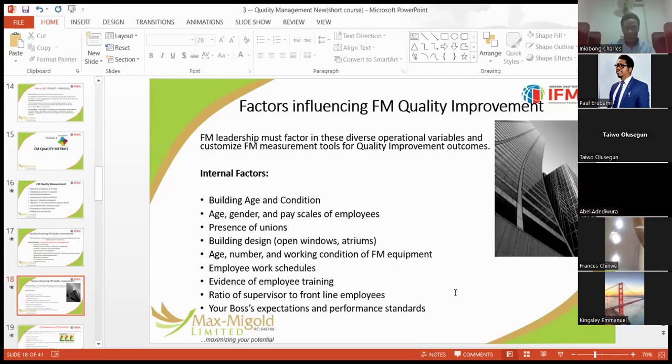Therefore, when we want to improve our quality, we look at the condition and we see what we can do. For example, for such a generator, you cannot run it for 250 run hours. You must reduce the run hours so that you can meet the maintenance need.